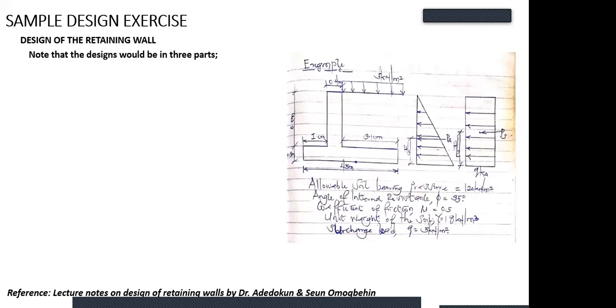So the other part is how we now calculate your reinforcement. What are the things you need to do to calculate your reinforcement? And one thing is common across all parts. You need to get your design moments, because from our knowledge of all those K equal to 0.15, all those stuff, what you just need is your bending moments, your maximum bending moments.